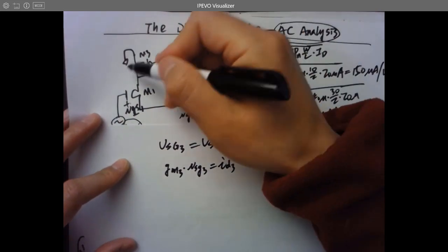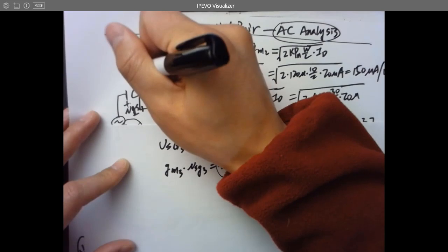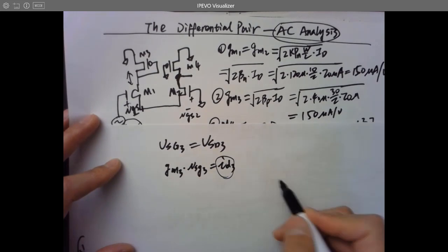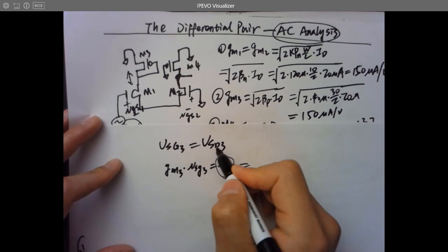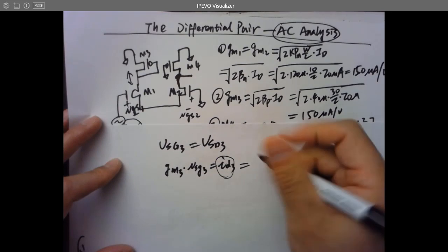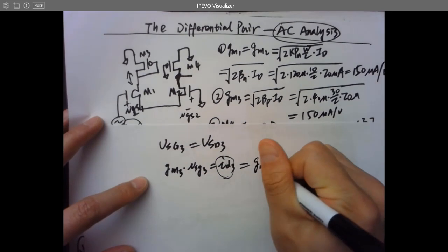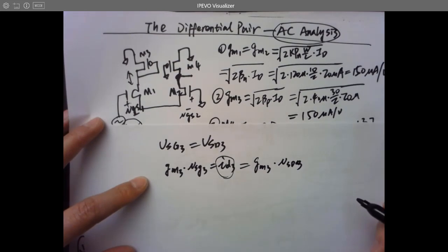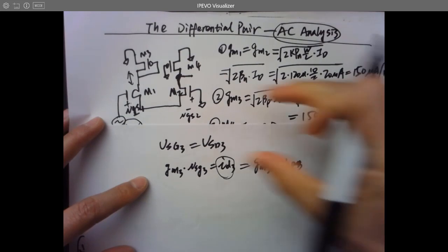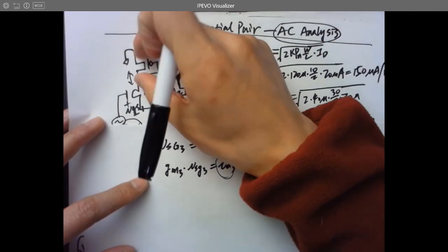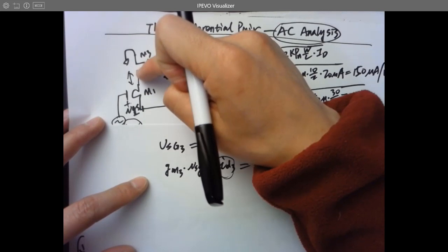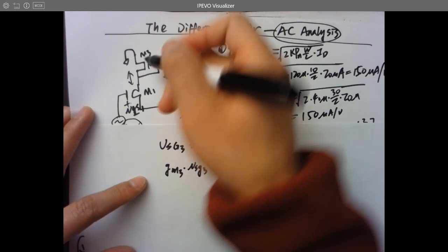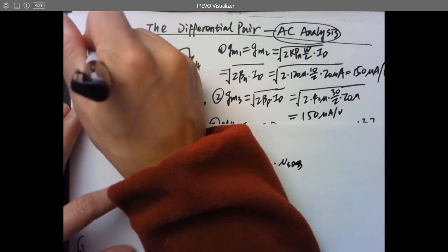Okay, so ID is the AC current oscillating in the channel. And we know that here's the equation. Because they are being shorted together, we know that ID3 also equals to GM3 times VSD3. Because VSD is the voltage drop across these two points, which is actually the channel of the transistor. Because in the PMOS, I know you have this connection, but the PMOS also has a channel, right?